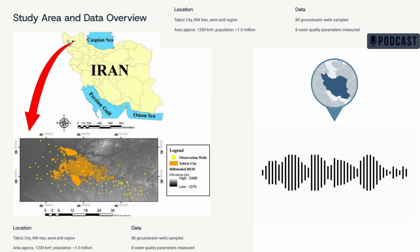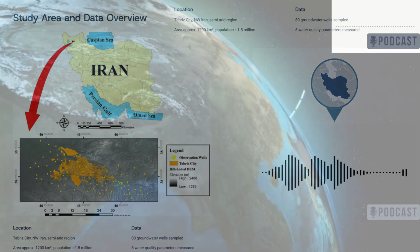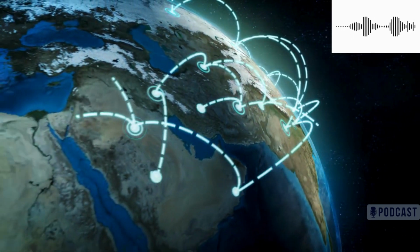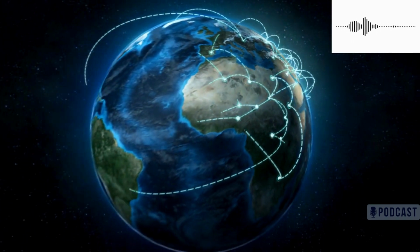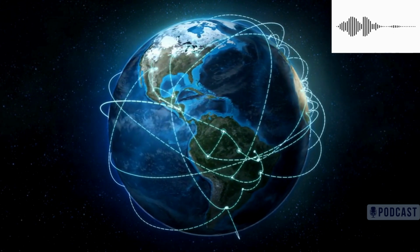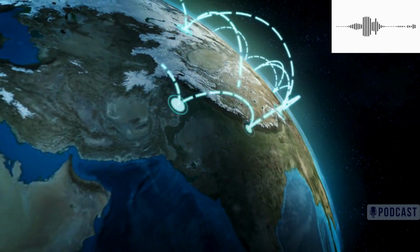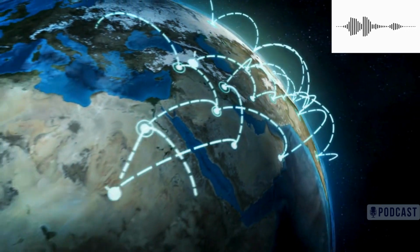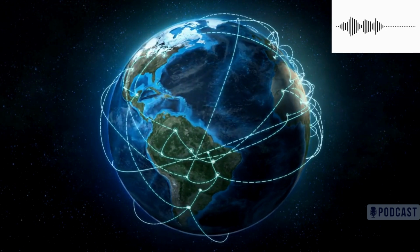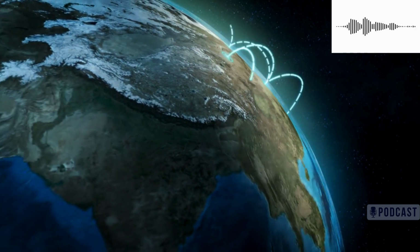Okay, cool. So the study itself is centered on Tabriz City in Iran, a place where water is obviously a very big deal. And what I like is that it's not just theory. They used real world data, right? From what, 80 wells? That's right, 80 observation wells. So it's grounded in actual measurements. And they combine these data mining algorithms with GIS, Geographic Information System. Ah, the mapping side of things. Yeah, to see which combination, which algorithm really nailed identifying those high-quality zones.